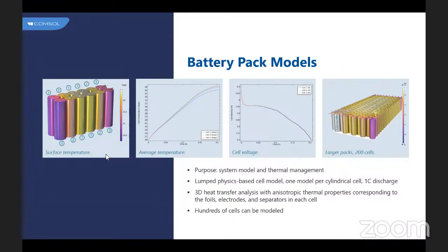You can find out the surface temperature. And you can actually also measure at different points. You can see the cell voltages, and also you can design different cooling techniques here and try to minimize the temperature rise in the battery pack.